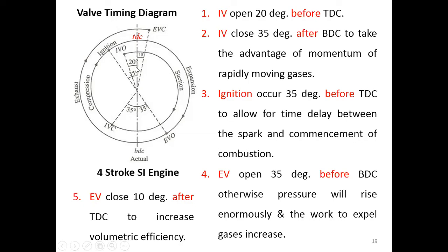So we have ignition early in order to allow for the time delay between the spark and the commencement of combustion. Because ignition happening doesn't mean combustion also happens. Combustion needs time, right? So ignition happens first and combustion takes time to occur.